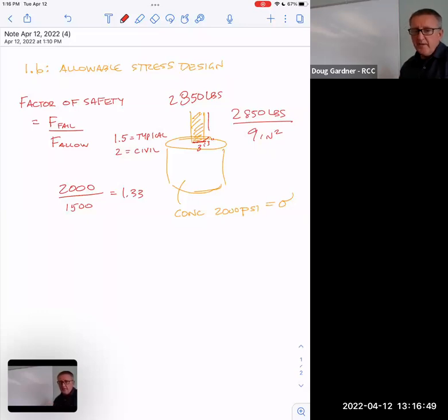And the other thing that I think is just kind of interesting to know, and we've talked about this some, but does it make sense the concrete manufacturer is saying, hey, this is 2,000 PSI concrete. It's not exactly 2,000 PSI, but remember, they've got to underpromise and overdeliver. In other words, if you did break that concrete after it was hardened, it probably breaks at 2,500, 2,800, 3,300. I mean, if they're going to say 2,000, then they're going to get sued if it isn't, or at least go looking for if somebody else screwed up.